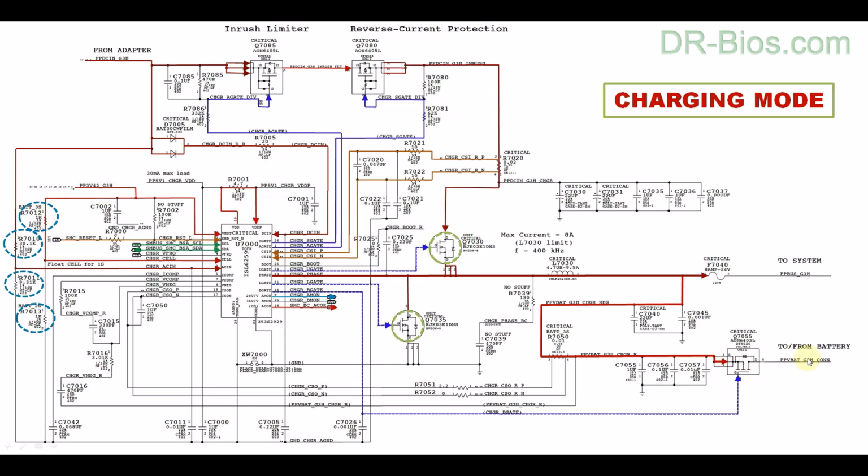During this process, IC gets sample of current flow intensity of two resistors. One of them is for adapter voltage and the other one is for battery voltage. It informs SMC about the status of current draw from these voltages through AMON and BMON pins, so that SMC could make proper decisions by monitoring these values.